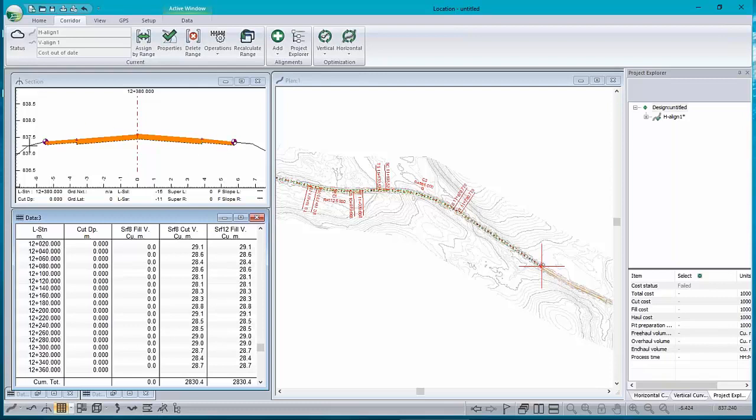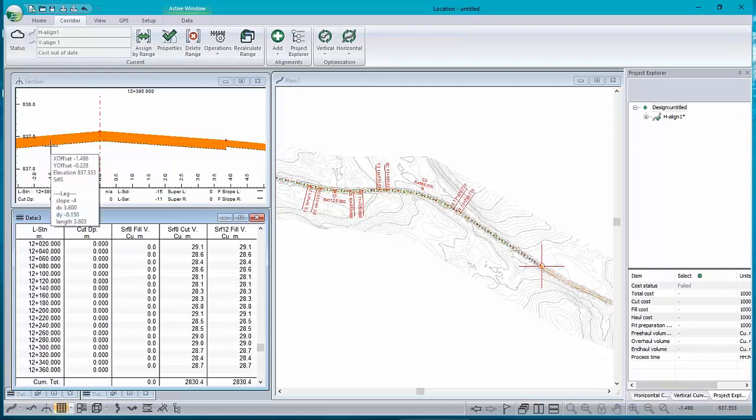And whatever the pavement was looking like, you can see in this particular cross-section, there's quite a large crossfall here. In fact, it is 4% on both sides. So maybe the shoulder has settled a little bit. It might have ruts in it too. It depends how the survey data was taken. If it was truly just surveyed on the paint line, then of course there's just a straight line between. But if we picked up drone data or LiDAR data, it might even show the pavement ruts, but it doesn't here.